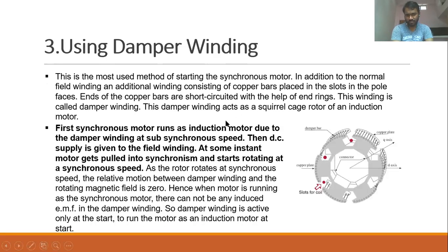And using the damper windings, we have discussed the damper bars many times, so let me explain in short. Here the synchronous motor acts as an induction motor, so there is no separate starting device. The damper bars themselves are used as the starting method. Initially, due to the presence of the damper bars, it acts as an induction motor, and we bring the machine to subsynchronous speed.